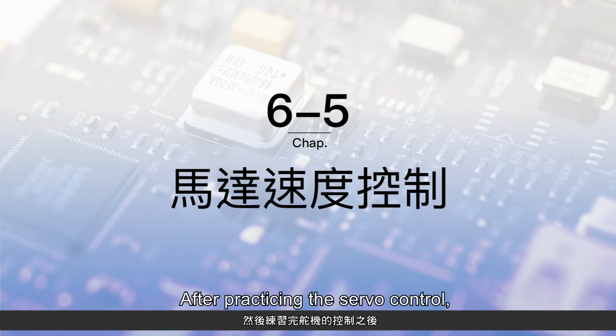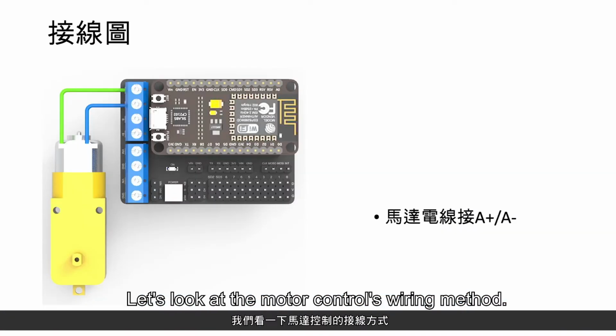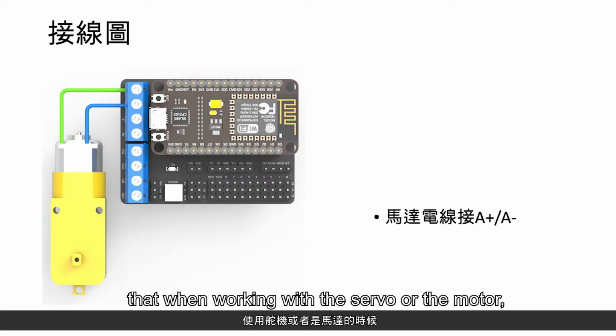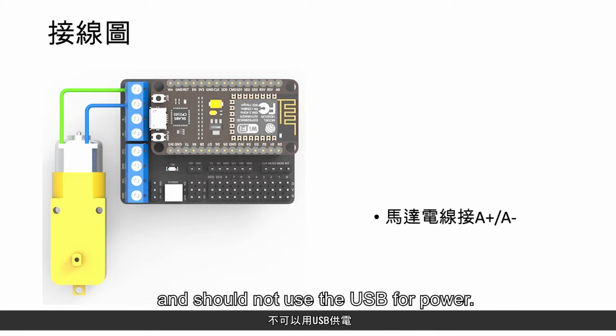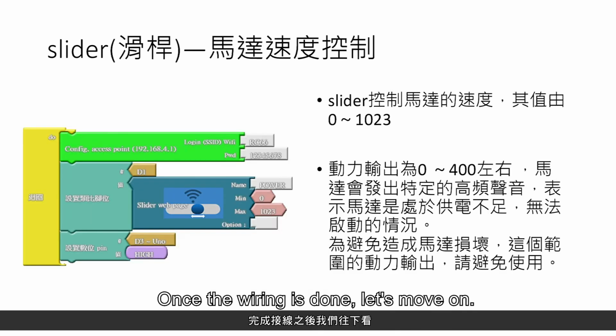After practicing the servo control, we will perform the motor control next. Let's look at the motor control's wiring method. Please do this wiring as instructed. Let me remind you that when working with the servo or the motor, we must have the battery box powering them and should not use the USB for power. Please develop this habit. Once the wiring is done, let's move on.